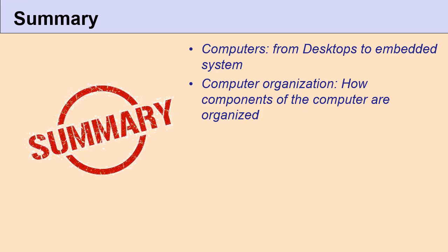We looked at how data can be transferred between these modules using the system bus: how an address is used to identify where the data should be sent to or read from, how we can use the data bus to send or receive data, and how we can use the control bus to send commands to those devices to act accordingly.